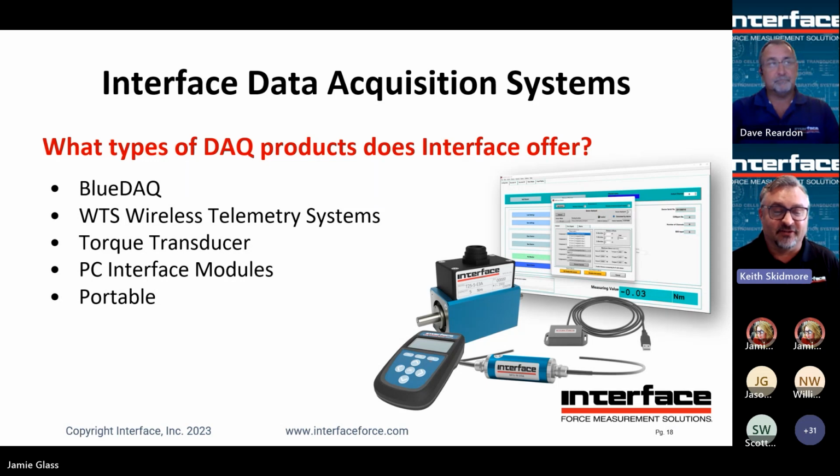There are various PC interface modules which take sensor inputs and convert them into a connection to the PC, and they come in different numbers of channels, single channel up to 8 channels, and then they can be combined for any number of channels by adding multiple modules. Again, some of them are portable, handheld with batteries. Some of them will log to an SD card, so they're completely independent of a PC, and then you can read the data later.